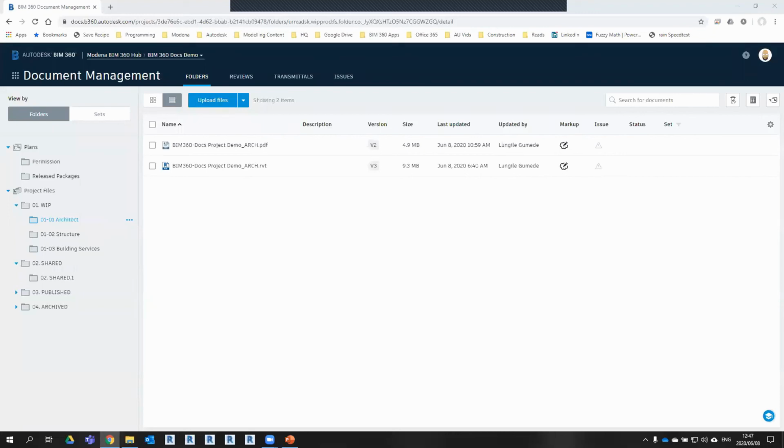And then you guys love to ask questions today. Willem, does the file size matter? Currently, no. Autodesk says it doesn't matter, although remember when you're working with Revit Collaborate, a local copy of that file is on your computer, which will then have an impact if the file size is too big. On the Revit side of things, or BIM 360, you can upload quite big file formats without any issues.